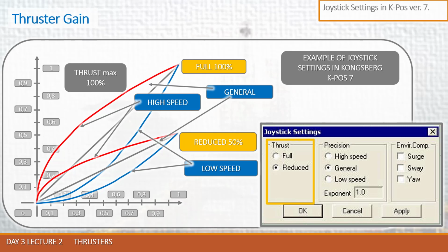There are three predefined controller gain levels available: high, medium and low. The selected gain level applies to any of the surge, sway and yaw axes when they are under automatic control and high precision or relaxed control mode. If configured, customized settings of the controller gain level can be performed with individual gain factor settings for the surge, sway and yaw axis. Different gain factors for each of the three standard gain levels are defined to suit the characteristic of the vessel.